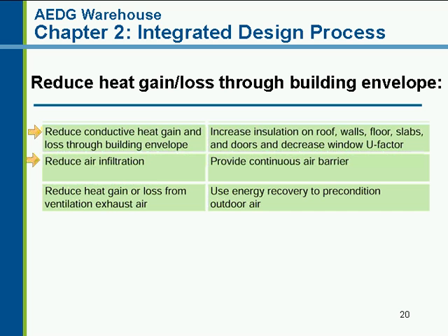A good way to check for this and check your performance is to have a blower door test done, where they actually bring a device up, which would be mounted, for example, in one of the doors of the building. They turn on a high-power fan, and then you can see how much pressure the building can hold, and that will tell you about air leakage. And a way to evaluate that and improve it is to use a smoke stick, and that will quickly show you where the air is going in or out of the building, so you know where you need some additional caulking.